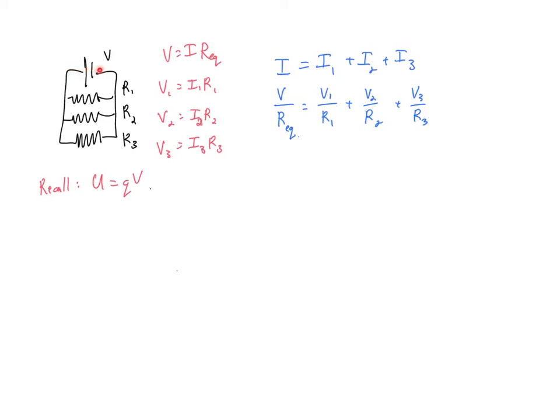So if I go from here, cross V, I now have a potential drop of V. But if I keep going along this wire, then I still continue to have a potential drop of V anywhere I go as long as I don't cross a circuit element. Same deal with going from here down. That's a potential drop of 0 because I haven't crossed any circuit elements.